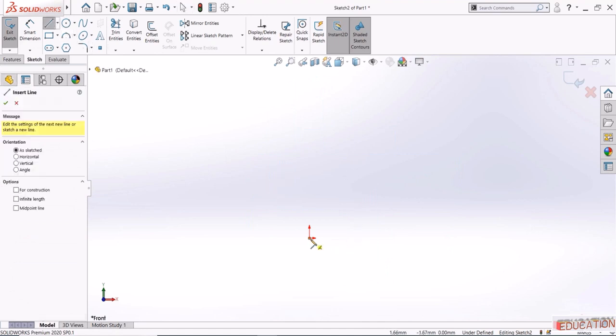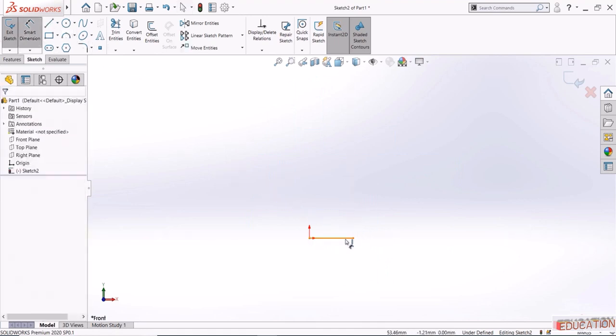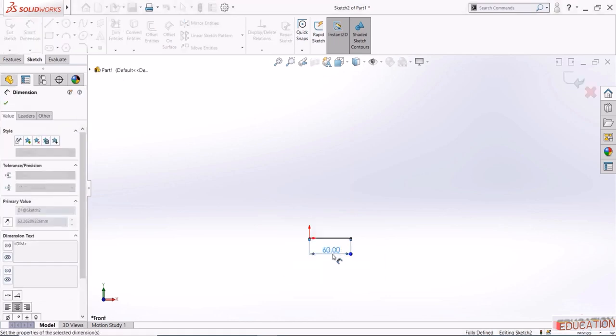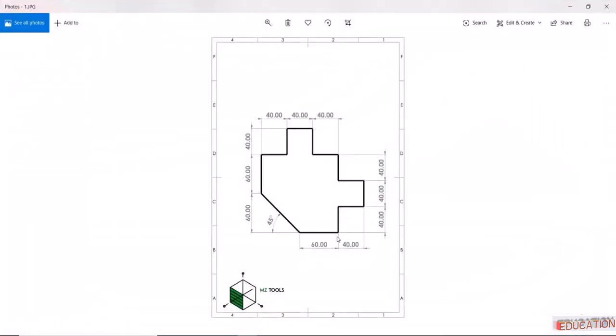The first line we have here is 60. Now, after that, I usually prefer to place the first dimension because this will fix the scale of the screen. Like, if you draw a line and then started to sketching all of these, then you started to place the dimensions, who knows, maybe the line you created is 1000, not 60. So imagine what will happen when you set it to 60. Then modifying the geometry will be relatively hard. That's why always place the first dimension, then start working.